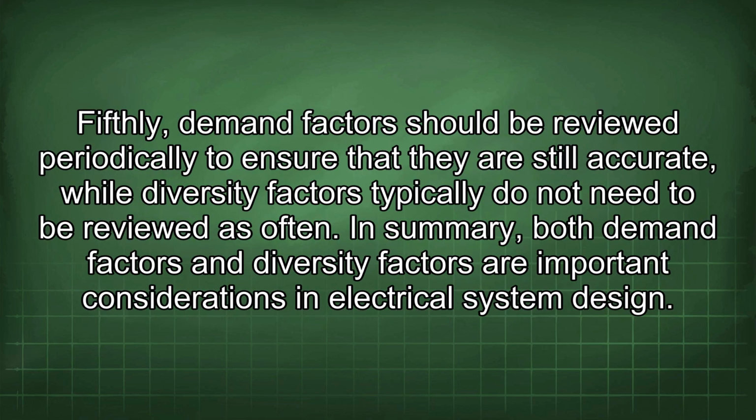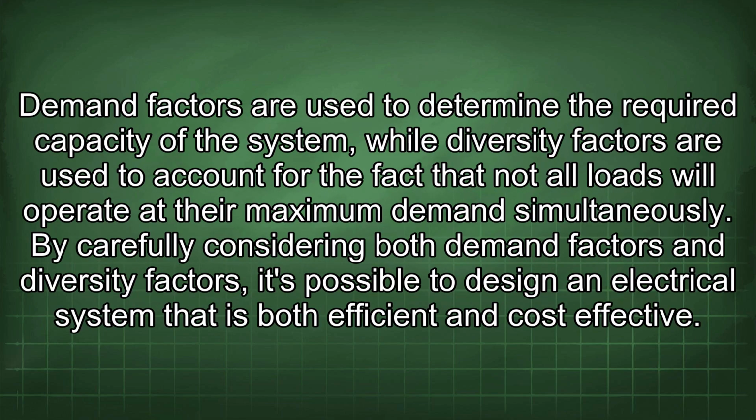Fifthly, demand factors should be reviewed periodically to ensure that they are still accurate, while diversity factors typically do not need to be reviewed as often. In summary, both demand factors and diversity factors are important considerations in electrical system design. Demand factors are used to determine the required capacity of the system, while diversity factors are used to account for the fact that not all loads will operate at their maximum demand simultaneously.